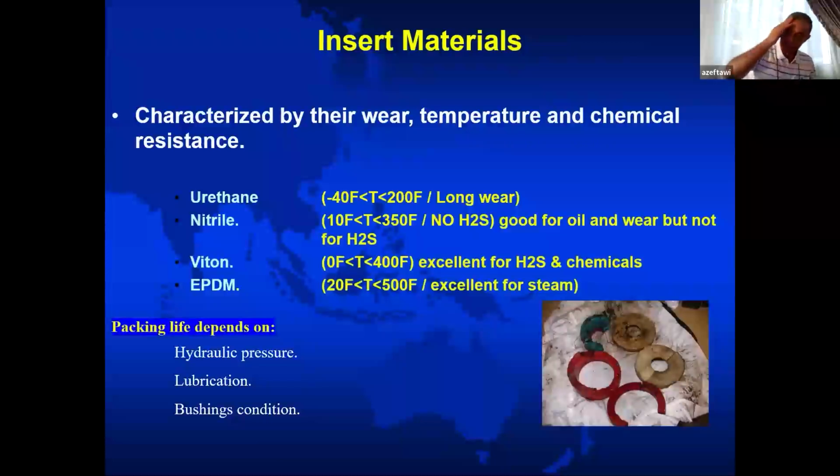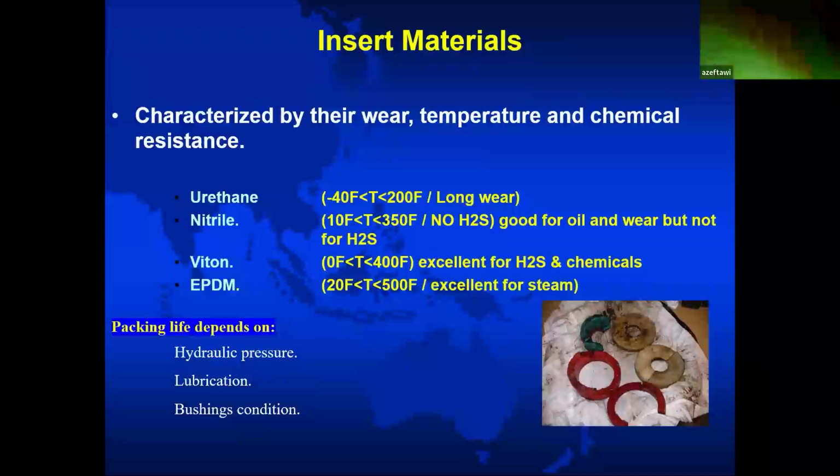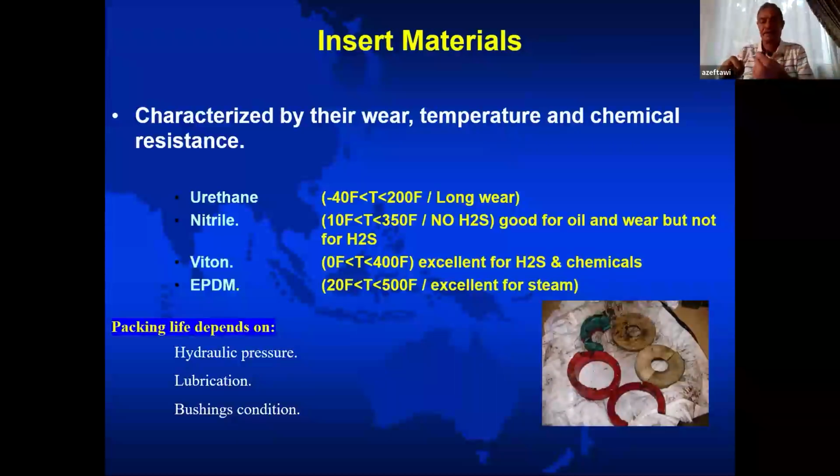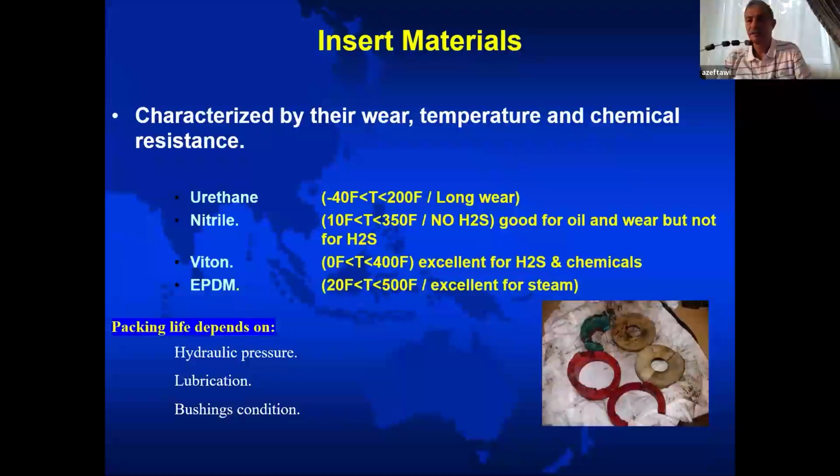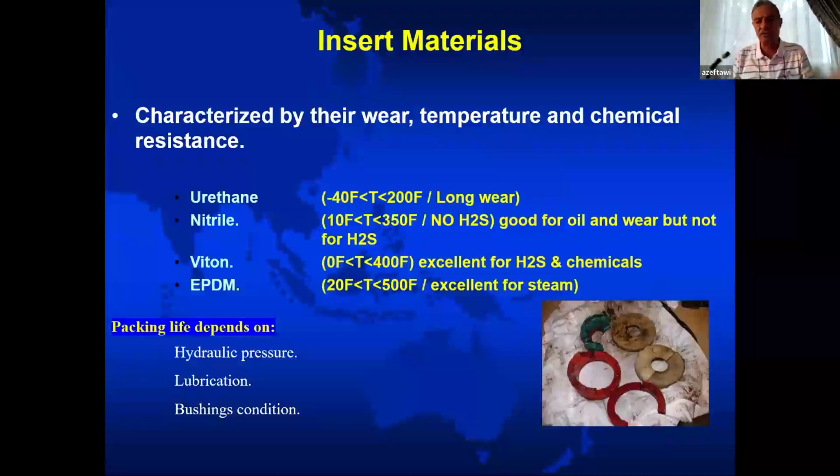As we discussed in the slickline, if you remember, I showed you that this is a slickline and these are different packings. Why different packings? Because it depends on the job I'm doing. Is it high pressure, low pressure, high temperature, low temperature? Is it sour or sweet? Is it gas or oil? And based on that, I will select the correct packing element.